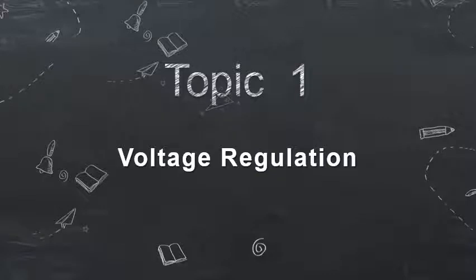Voltage regulation is no load voltage minus full load voltage, divided by full load voltage, into 100%.